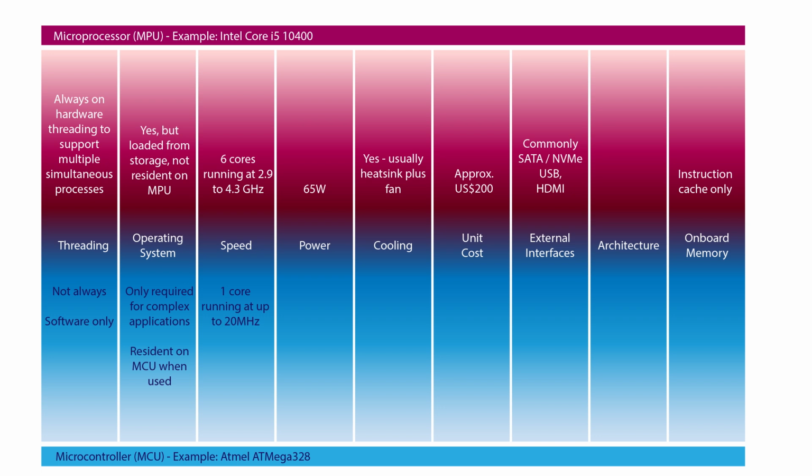But the point is, that level of power is sufficient for running a single application like a traffic light controller. And the advantage of this lower power is that the energy consumption is much lower too, maxing out at about 100 milliwatts. And that means we don't need to add cooling systems like heat sinks and fans, all of which adds up to much lower running costs. And while we're talking about cost, the ATmega328 retails at less than $2 per unit, 1/100th of the cost of the i5.